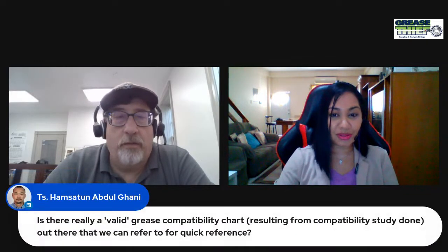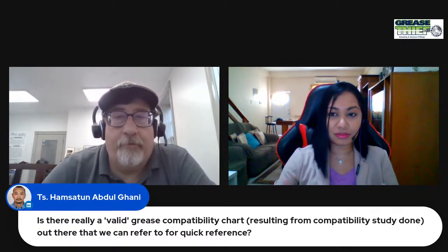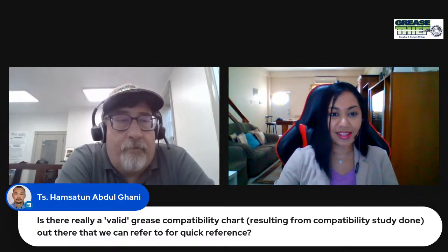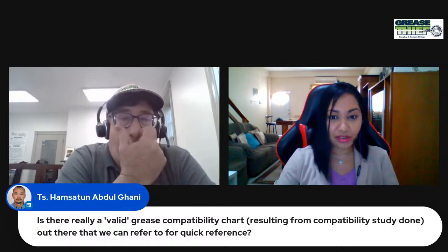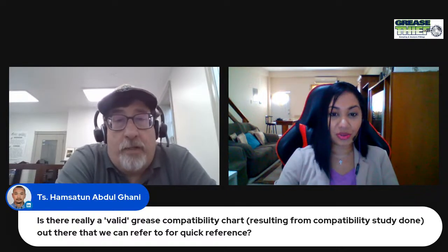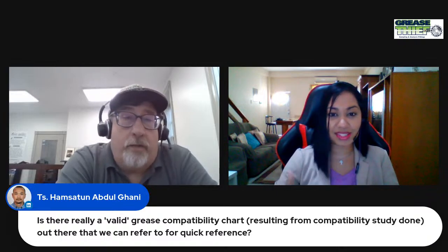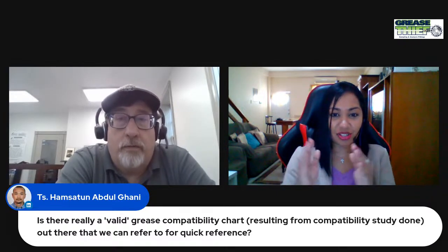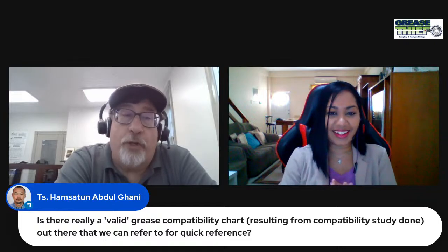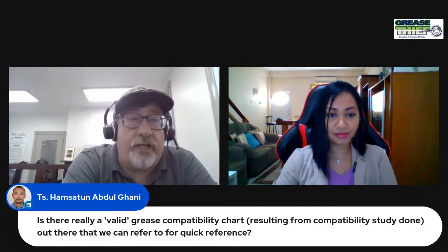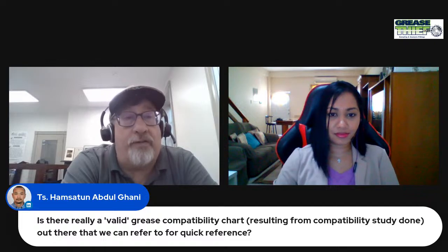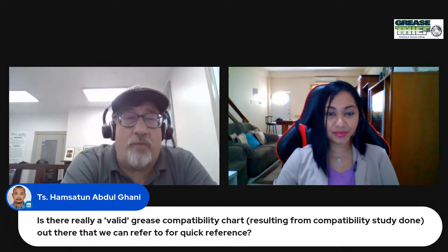Now, the first question that we had, Hamza asked, was there any sort of valid grease compatibility chart? Something that has been done that people can use as a reference? And I know you talked about actually physically doing that test because that helps in knowing the environment and what else could be involved, because sometimes these charts are controlled testing. So what I would say is have a questioning attitude. If you have a compatibility chart, the first question I would ask is what data was used to compile the chart?